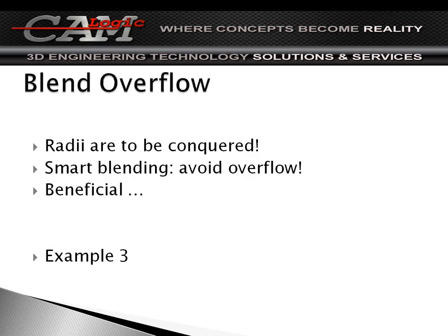All right, on to blend overflow. So don't let your radii beat you. Don't let your rounds and fillets and blends take over just because you have too many all in one area and you get tied up. I've seen it, in the past where, sometimes it'll crash apart just because your blend overruns into another blend. So, in NX 7.5, it's definitely not the case. Sometimes your blend might not come out perfectly, but it'll give you a shot at blending a little bit cleaner, no doubt.